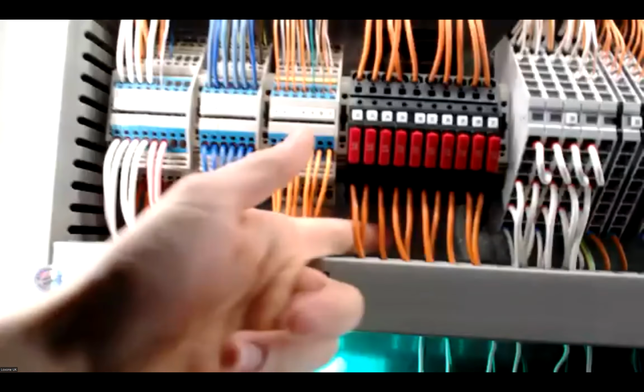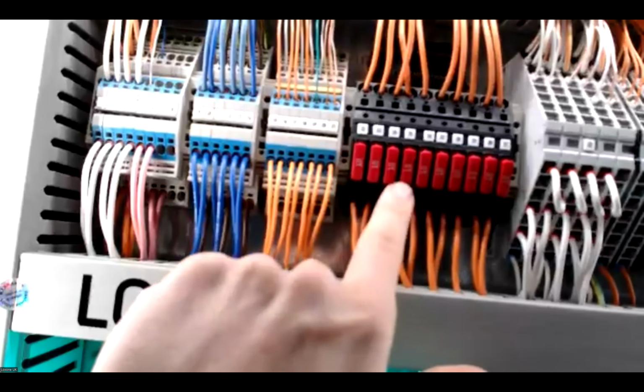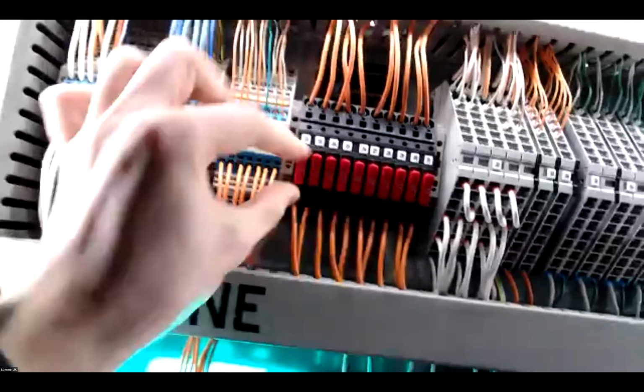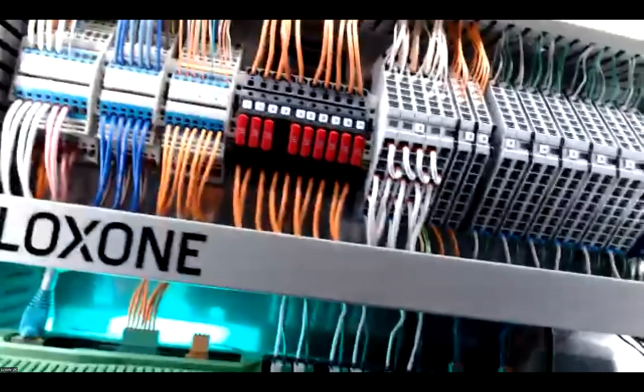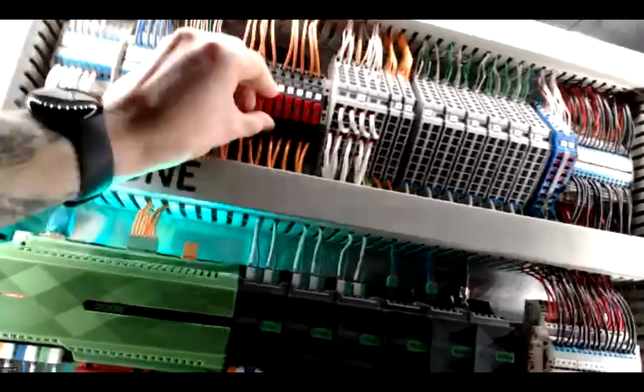We have the blade fuses. So this is for our lights. So for example, if I pull one of these fuses, I don't know if it's the third one or the fourth one, but let's see. Yeah, it's this one. I pulled it off. And what happened in the room that I'm currently in, the very last circuit of lights switched off. So now I can safely go ahead, and if I need to do some work on that circuit, I can. And also, obviously, everything's fused, so I do have my backup in place. And as soon as I push it in, there we go. Connections back in. Perfect.